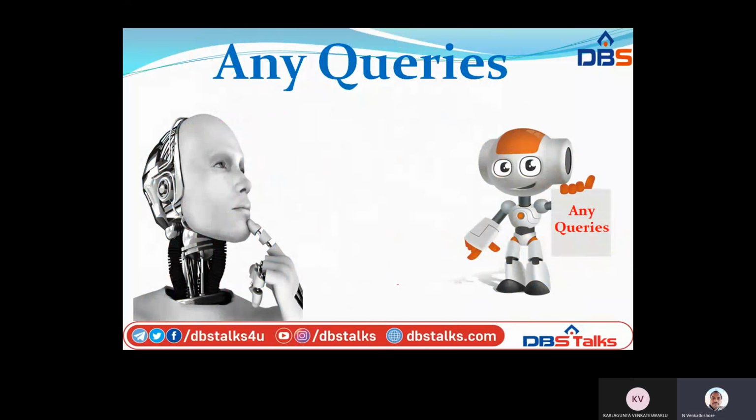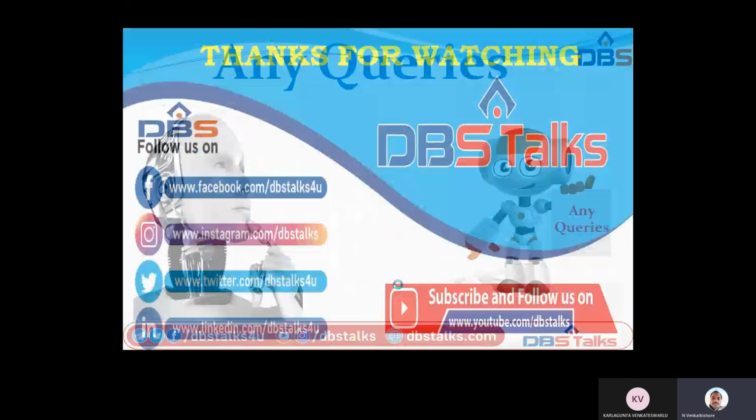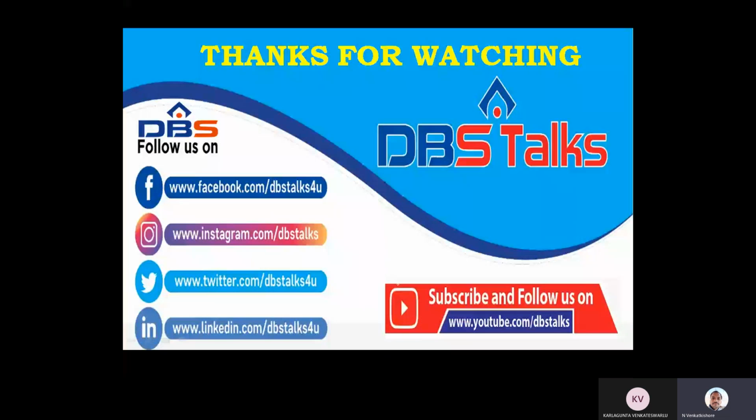So this is today's class, the final session on simple mechanisms. Firstly, the single slider crank mechanism is divided into five varieties. One is the pendulum pump or Bull type engine. The second one is the oscillating cylinder engine. The third one is the crank and slotted lever quick return mechanism. The fourth one is the rotary internal combustion engine. And the last one is the Whitworth quick return mechanism. Then finally we will see the animation of this Whitworth quick return mechanism.